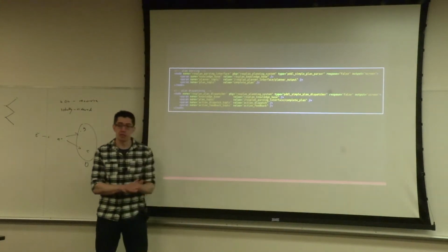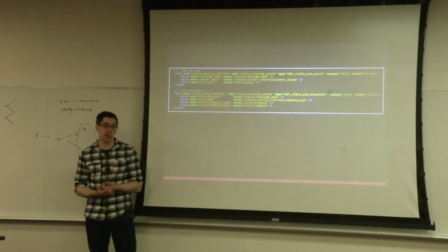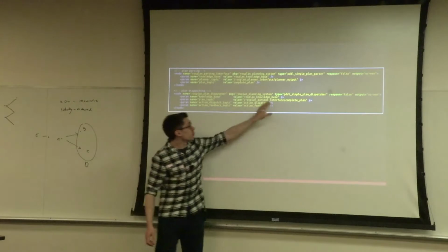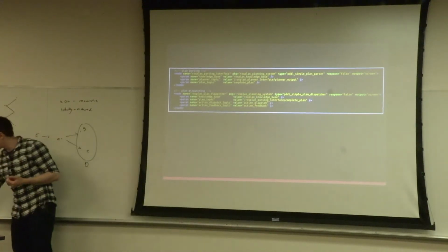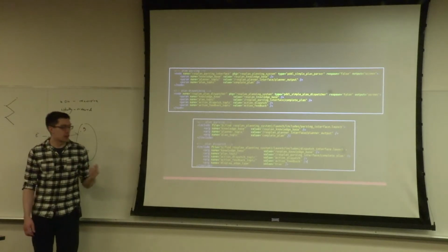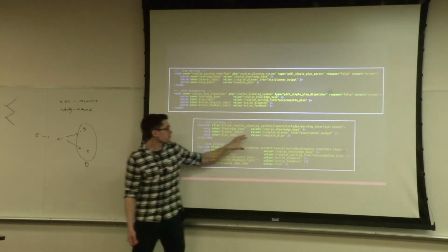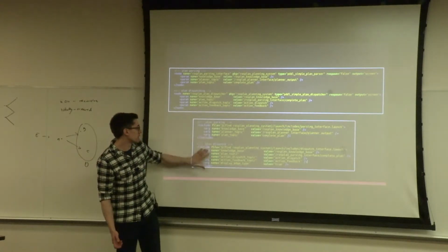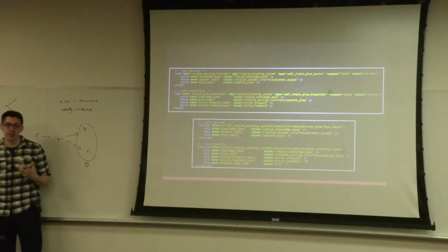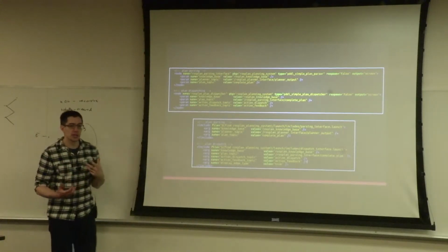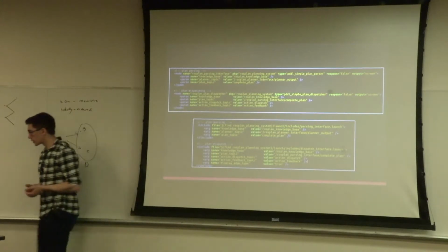There's one difference between the example system you'll launch from our ROSPlan demos package, and that's we don't use the simple plan parser and the simple plan dispatcher as the defaults, mainly because they're just not very good for robotics. Instead, we launch what we call the STRL plan parser and plan dispatch. So this is a plan dispatch that's actually able to execute plans with concurrent actions and temporal constraints.